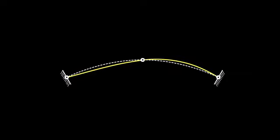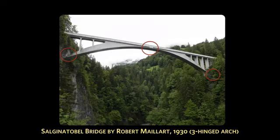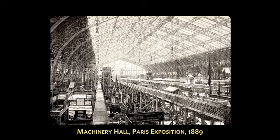To reduce and/or control the bending stresses in arches, we can introduce what are called hinges. A hinge is defined as part of the structure that does not resist rotation. Think of a hinge on a door. That hinge will allow the door to swing freely without any resistance to rotation. Bridges are often designed with hinges. For example, Robert Maillart's Salginatobel Bridge is a 3-hinged arch bridge. This concept of 3-hinged arches can be extended to long-spanning roofs. It was applied as early as 1889 for Machinery Hall in the Paris Expo.